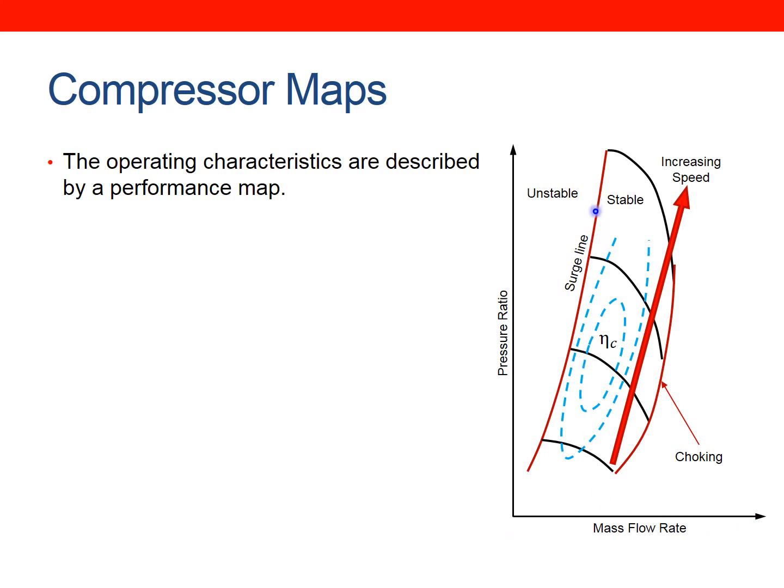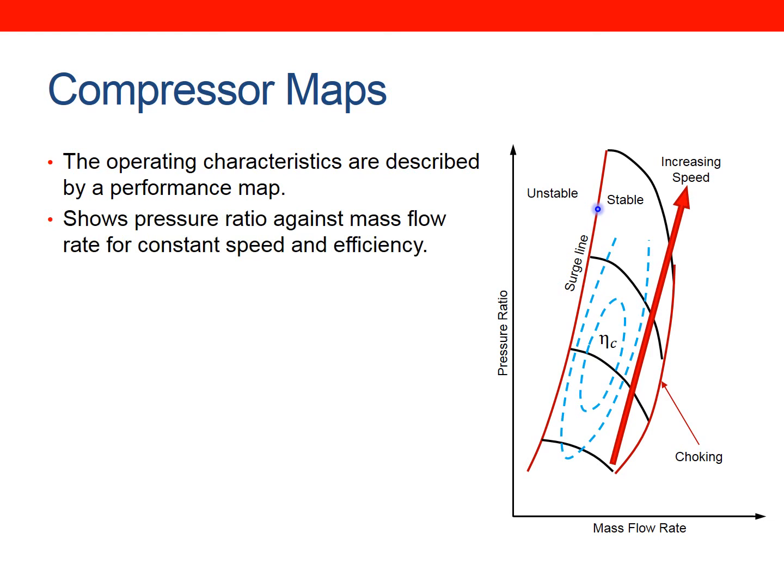And what we've got plotted here is two things: plots of speed, this is compressor speed, and also in the middle we have so-called islands of compression efficiency. So you can read this map in a few ways. These black lines here are compressor speed, and this is compression efficiency.